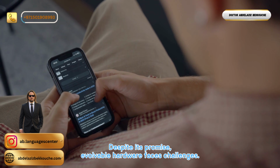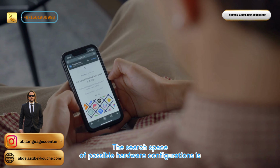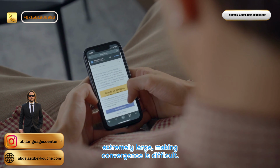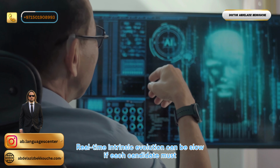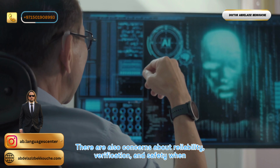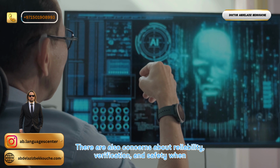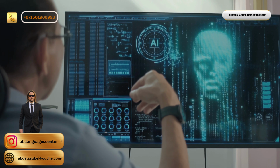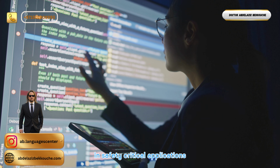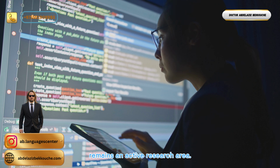Despite its promise, evolvable hardware faces challenges. The search space of possible hardware configurations is extremely large, making convergence difficult. Real-time intrinsic evolution can be slow if each candidate must be physically tested. There are also concerns about reliability, verification, and safety when hardware autonomously modifies itself. Ensuring predictable behavior in safety-critical applications remains an active research area.